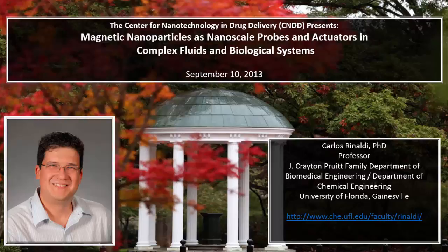So with the polyethylene glycol particles, another example of this idea of making nanoscale and macroscale measurements is to use it to determine a so-called gelation temperature for a simple system that gels with temperature. In this case, I'm showing you data for solutions of gelatin, 10%. And you can measure gelation temperature rheometrically, or using viscosity measurements, by measuring viscosity as a function of temperature at a fixed shear, or by doing small amplitude oscillatory shear experiments and looking at where the in-phase and out-of-phase moduli cross.